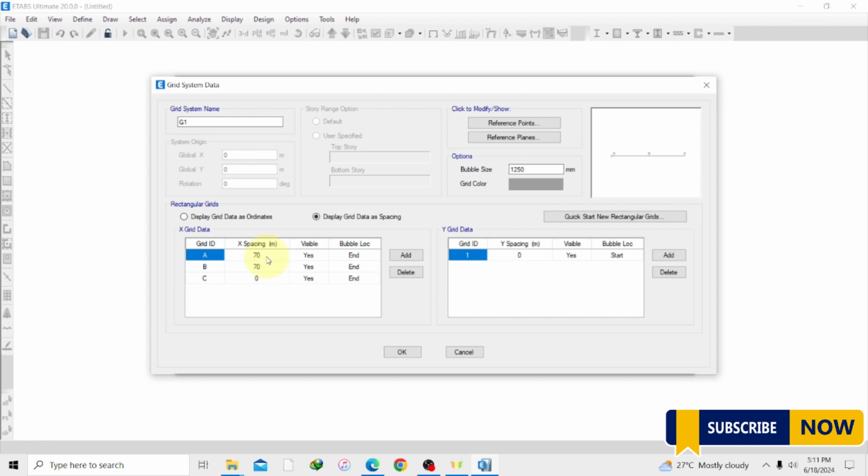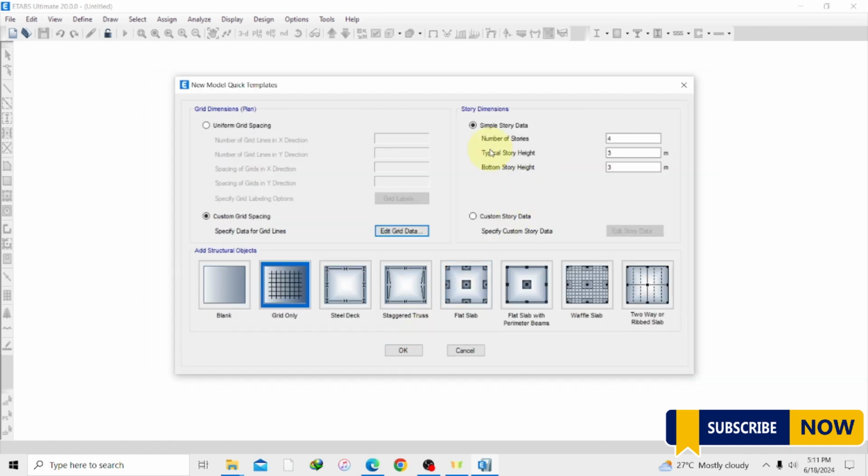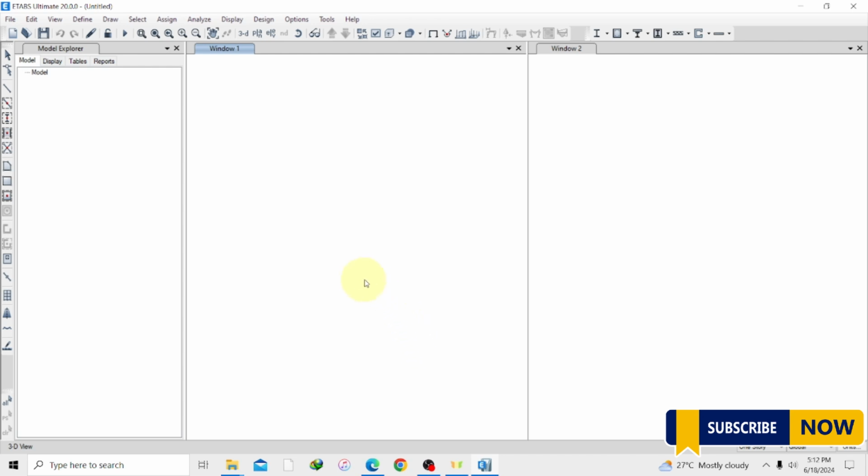They have different measurements but of the same model. So once you are done specifying, you just have to click on OK. And we have a number of stories, just like the model we first did is just 1. Typical story height. I'm just going to leave everything like that. And once you are done, you select grid only, then click on OK.